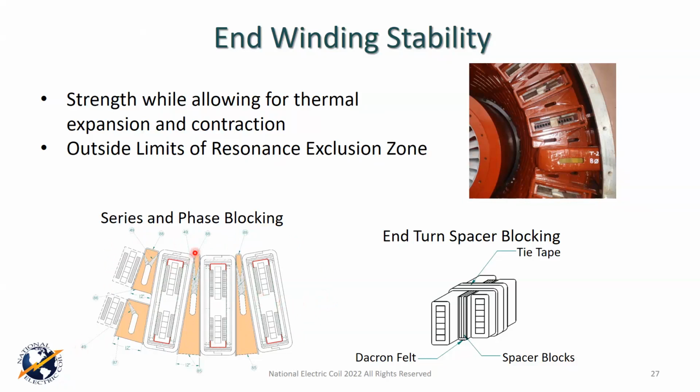You can see those tapered blocks. You can see them up here in the picture in between. The reason they have this hole in the center, you can see the lacing that's going around. So not only are they put in tight, but they're laced tight. Now there are a lot of designs where this tapered block is actually in two or three pieces.